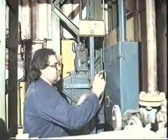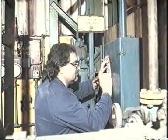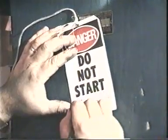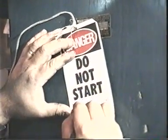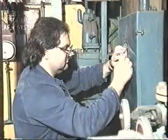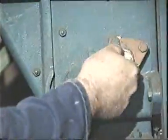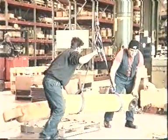The crane isolator should also be tagged to warn people not to use the crane until it is repaired. The tag needs to be signed by the person who detected the fault and should only be removed by that person or a qualified crane maintenance person. If you do not have a written checklist, then pause this video and make a note of these important items.